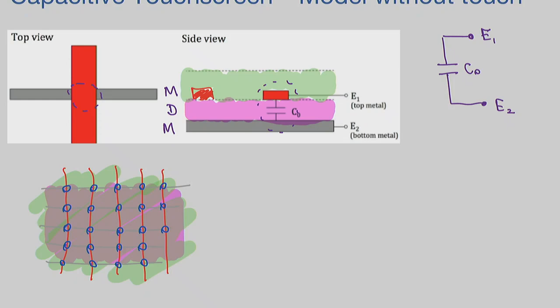It's going to depend on the permittivity of the material. Whatever material we chose, if I chose a polymer, which I always choose because I work on polymer electronics, I know that the permittivity is low, so I know how to calculate my C naught. If you, in your devices, you probably have much better dielectric. So he said C naught is going to depend on the permittivity of the material.